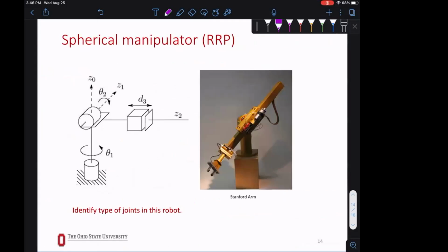Now, what if we had a prismatic joint? So here is your joint variable. You'll see better here what it is. You create a vector, call it the joint variable, and then you put your variables in there. So my Q has 3 elements that shows I have 3 joint variables, theta 1, theta 2, theta 3.